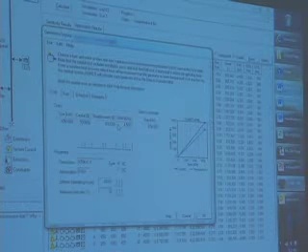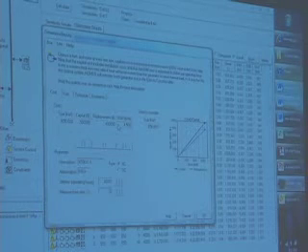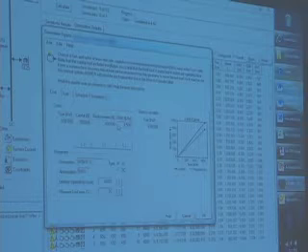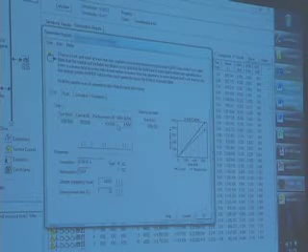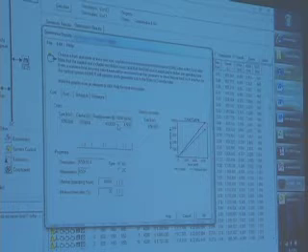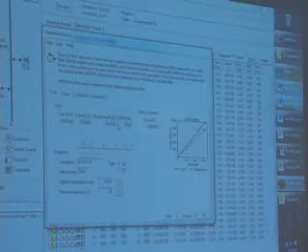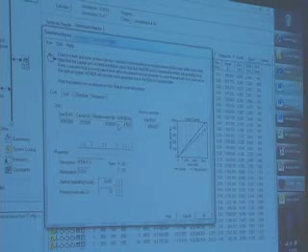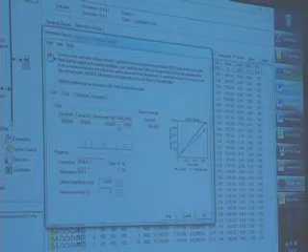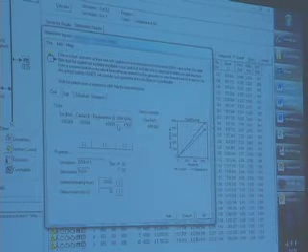But for diesels, it's dollars per operating hour, which is the way costs for diesel actually are incurred. You see studies where they talk about the O&M costs of different generating technologies in terms of cents per kilowatt hour. But that's maybe convenient for the analyst writing that white paper or something, but it's really not the way costs for a diesel generator actually are incurred.